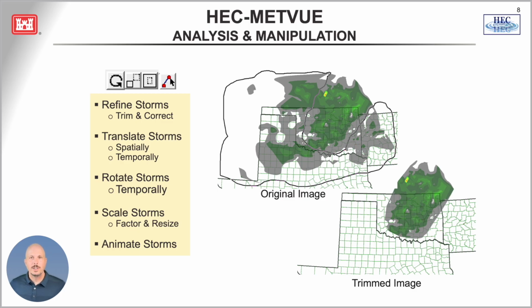The Resize tool, the icon to the left of the Draw tool, allows for expanding or shrinking spatial extents of a grid set. As tempting as it might be to use this tool, I do caution users to only use it in modifying data sets for testing purposes and testing purposes only.